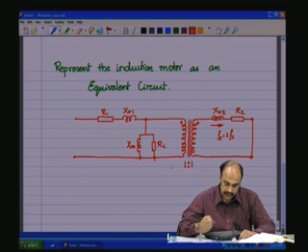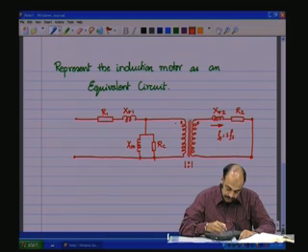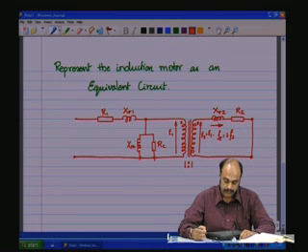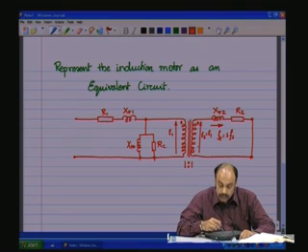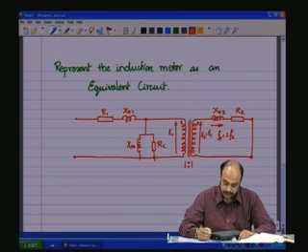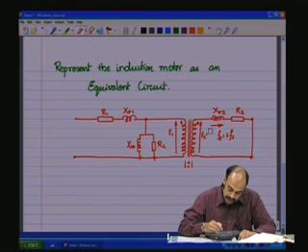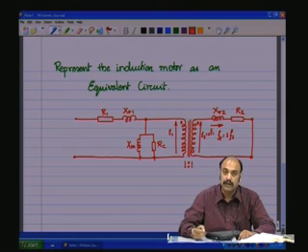Now as this is 1:1, whatever we have as the back EMF here, which is, let us say, we call it E1, we have E2 equal to E1. And the induced EMF on the rotor side, E2, is equal to E1 if it had been standstill, but would be equal to S times E1 because of the rotation that we saw earlier. So this is S times E1.